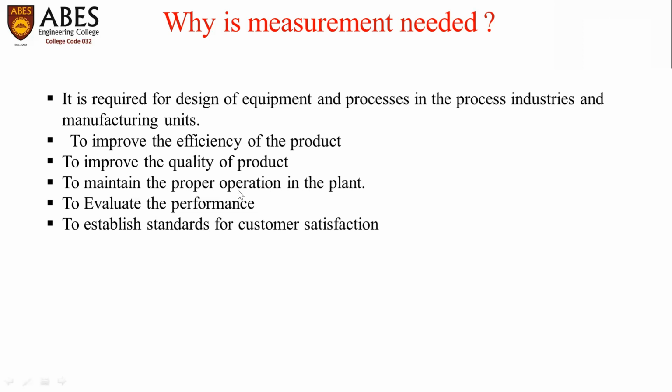So if I want to use the temperature sensor for monitoring the temperature of the boiler unit, I need to check which type of temperature sensor I'm using there, and what the temperature range is in which the boiler is working or operating. And for that particular range, is that type of sensor suitable in that working condition, or is it not suitable? I need to check its limitations, and then accordingly I will buy that product, right?